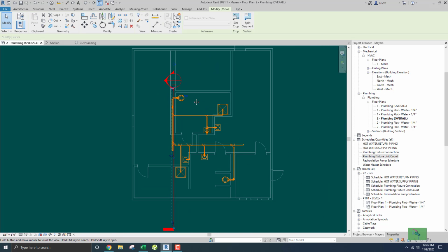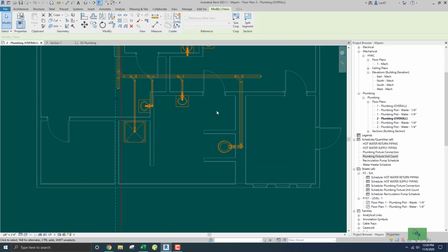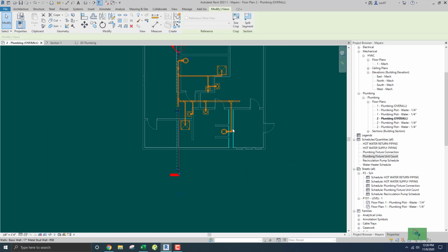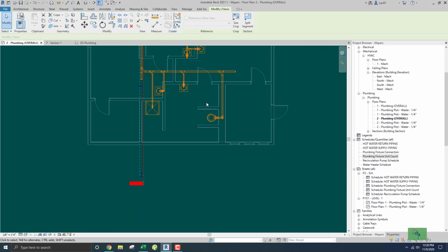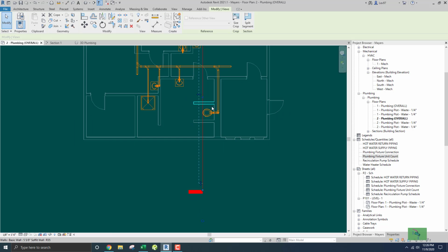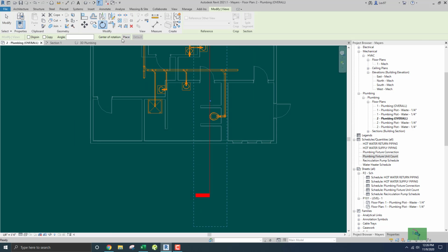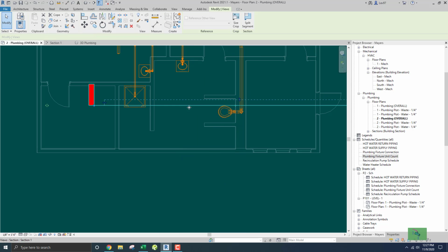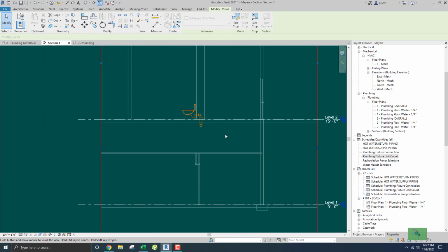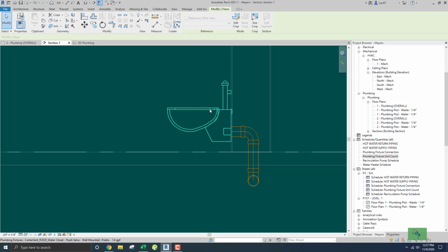So I'm going to vent, but I need a place. Let's bring all the vent and collect all the vent and use this as my vent riser. So let's do that. I'm gonna bring this guy over, use that as my vent riser. Let's rotate so I can see what's going on with my water closet, and in terms of my vent riser, that's cold water, and the vent is down here.